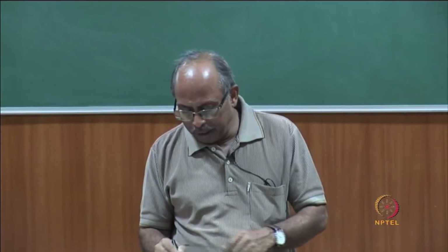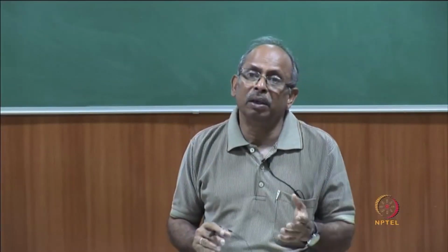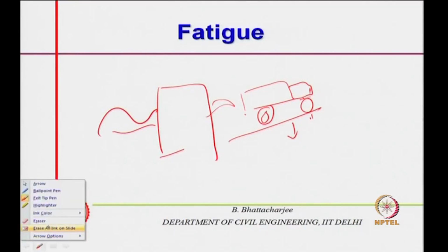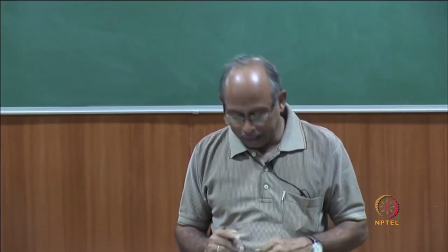In bridges, vehicular load comes onto the bridge deck, and then it moves. So, there is a reversal of stresses onto the deck. Therefore, this reversal of stresses is related to what is called fatigue strength. Okay. In fact, the load any structure or structural element can carry under reversal of stress is much lower than the load it can carry in static conditions.